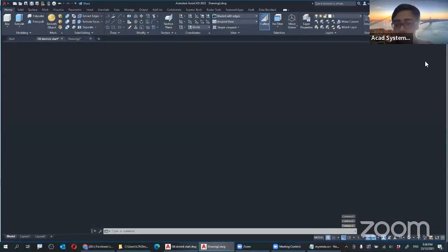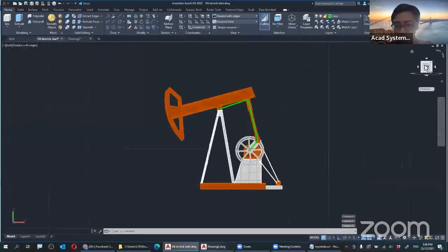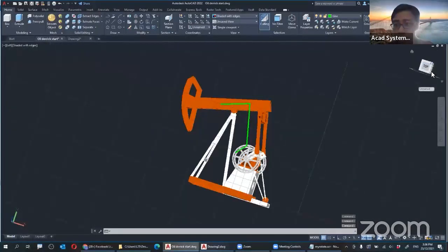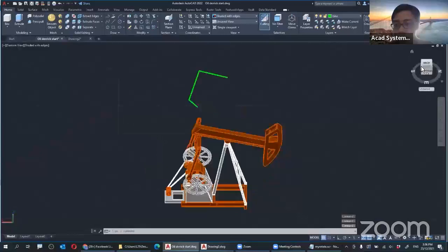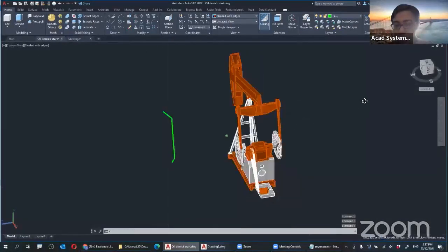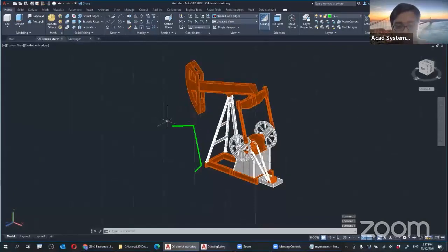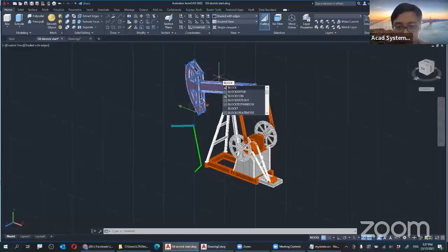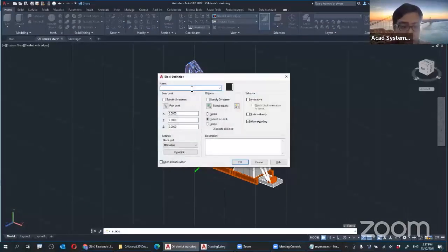So all we need to do is simply apply the same method that we have over here. Right, but not just yet, because we needed to create a block which will have the connection between this line and also this movement over here. So this line and this item over here, so I'm going to create a block. So I create block command, so BLOCK or block, press enter. I'm just going to name this one as, let's say, 1.